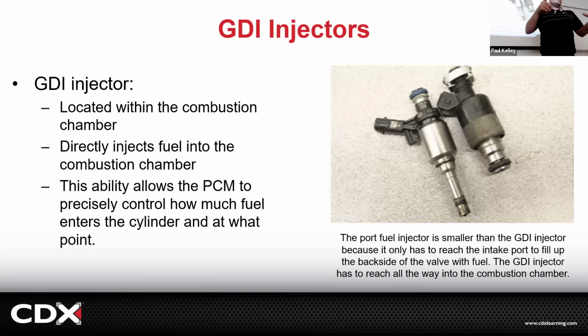All new seals. But the thing is, I don't have the special service tool, and the special service tool is kind of pricey. And plus, by the time that compression had blown by, I'm kind of sketched out with that injector. So I was like, hey, you need a new one? But if I have to unseat 4 of them to change one new one, and I don't have the tool, I had to sell them all 4.